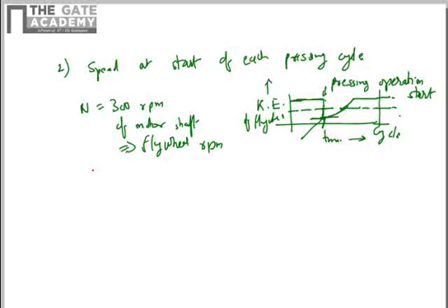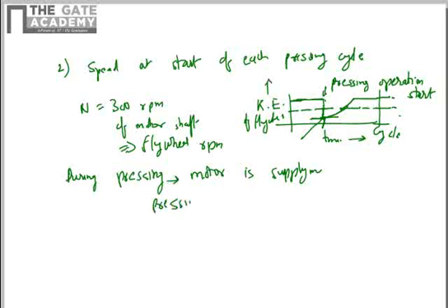When the pressing happens, the pressing machine absorbs energy from the flywheel, but during pressing, the motor is also supplying power, and the pressing machine is extracting power. So during the pressing, we will calculate how much the motor is supplying.